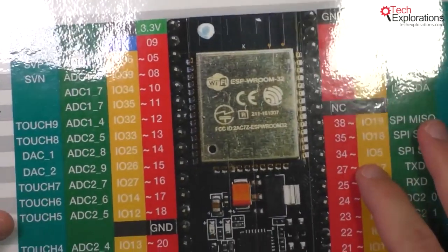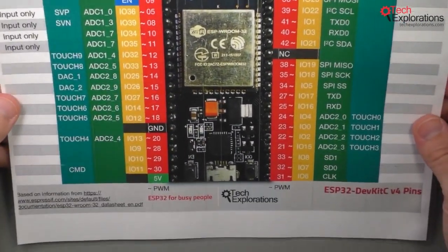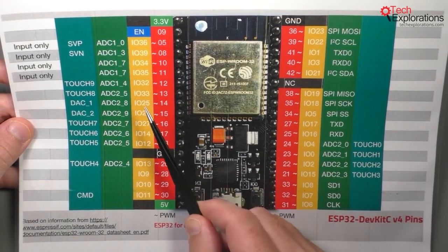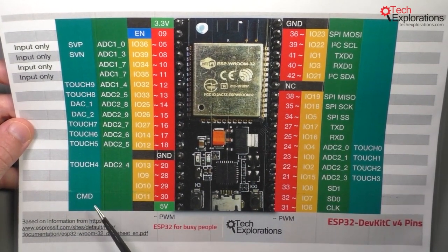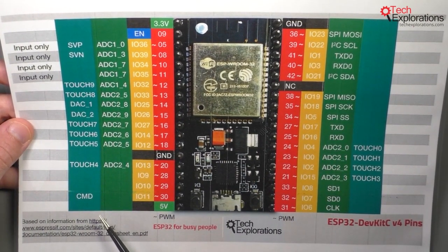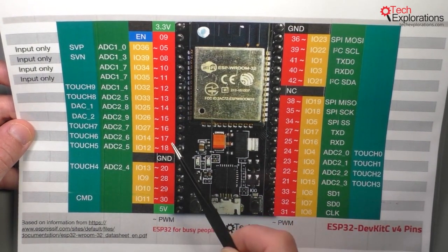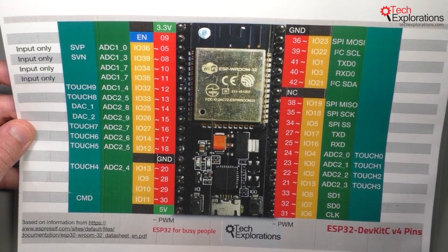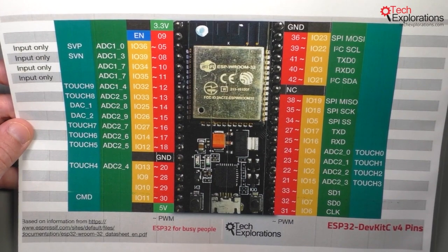Having a quick look at the pin map of the ESP32, just zoom out really quickly, there you go. You know that we can control an LED using any of the digital output pins. So we've got quite a large selection of those pins, those GPIOs. You can use the same pins as inputs and use them therefore to read the state of push buttons. And in an upcoming lecture, I'm also going to show you how to read the state of potentiometers.